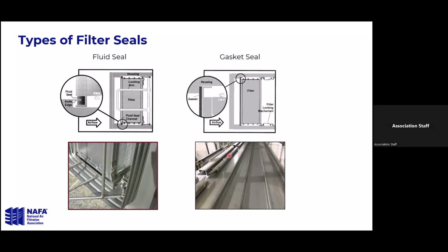When it comes to picking either a HEPA or a HEGA, remember I mentioned particulate would be your HEPA. So if what you're moving is a particulate, you use a HEPA filter. If it's more in that gas range, you're going to have a HEGA to effectively remove that. I know sometimes we get the question of isotope removal. Isotopes can be either a gas or a particulate.